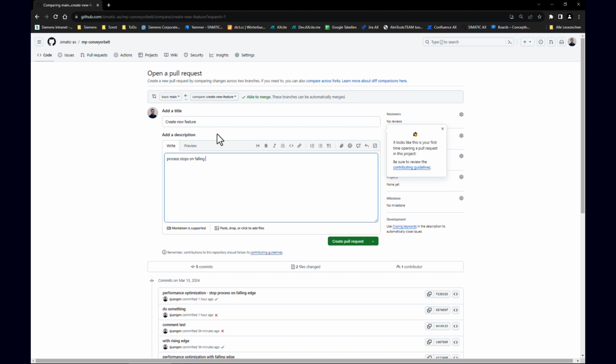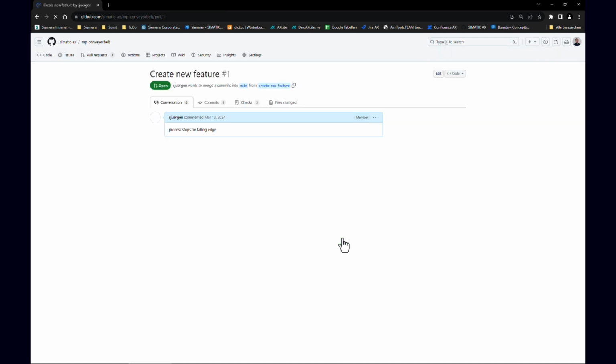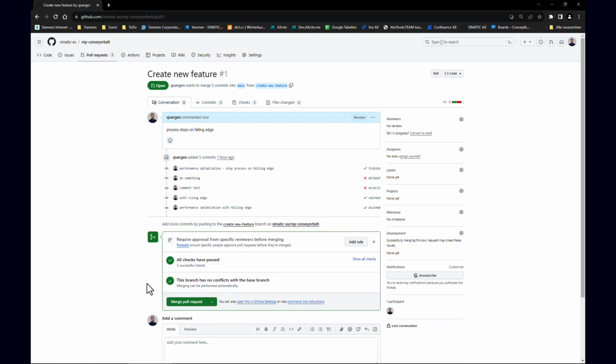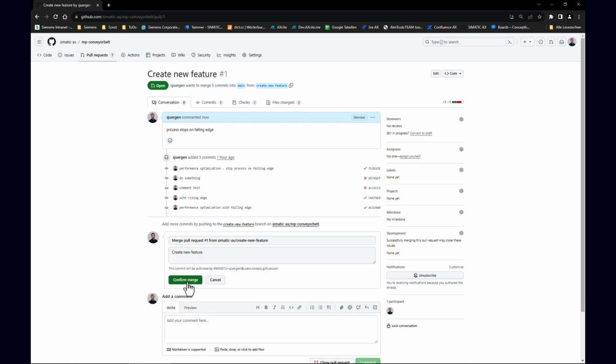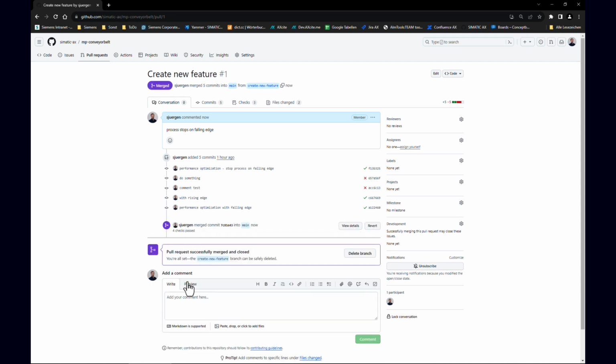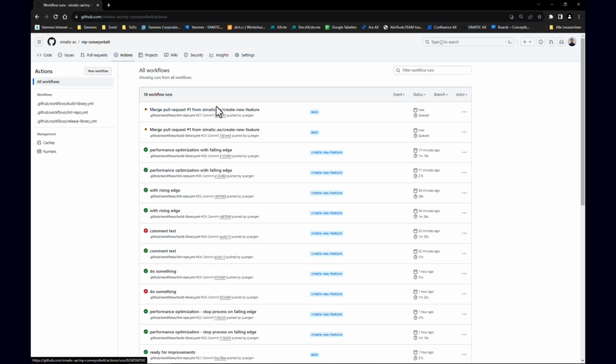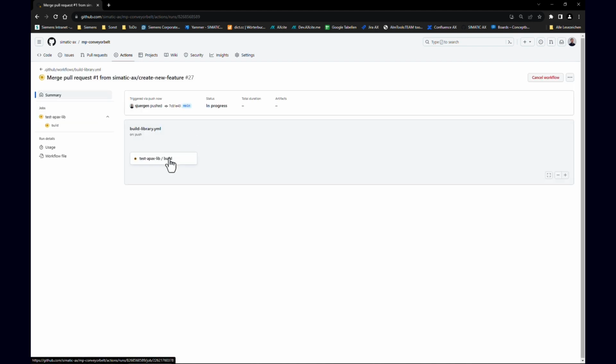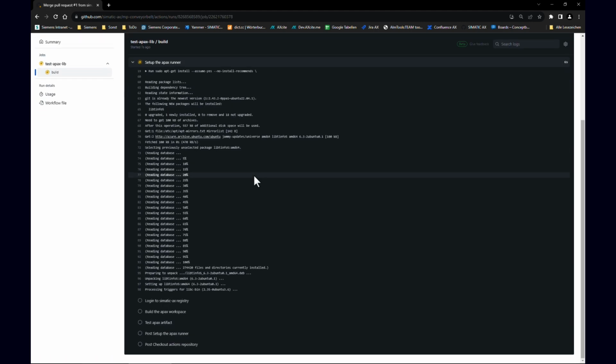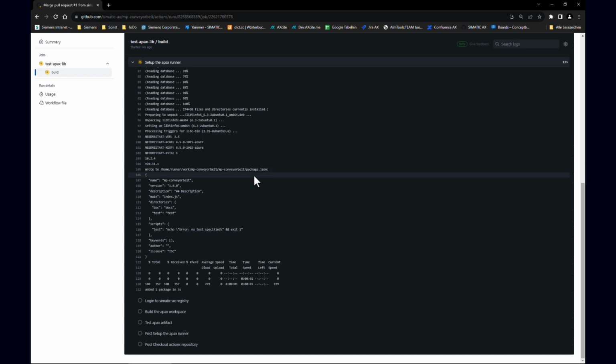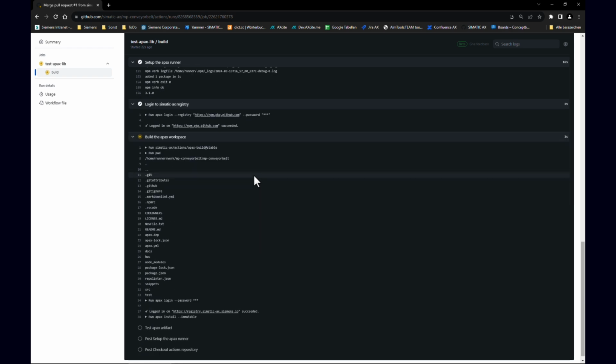We start by creating a pull request to get the commit. We then add a description and then merge the code with the project. This starts some pipelines, and within them, individual jobs or tasks that run automatically in the background. For example, it installs SIMATIC AX, it logs into it, it builds the project, it compiles it, and then it finishes. It then runs a test job to run unit tests, and if they are successful, everything turns green, and we are ready for the release.